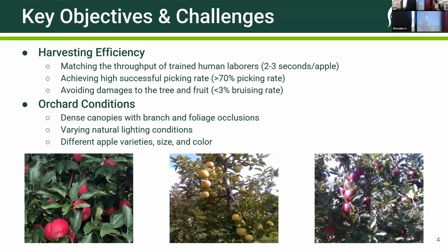We have been working with growers across Michigan, Pennsylvania, and Washington extensively to understand their needs and their requirements to design a robotic system. So I'm listing a few major metrics for success. The first one is the throughput or the efficiency. We're talking about this two-arm module, which should be comparable to one human picking laborer, who can pick fruits at 2 to 3 seconds per fruit.